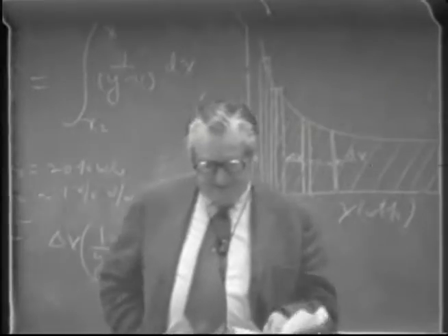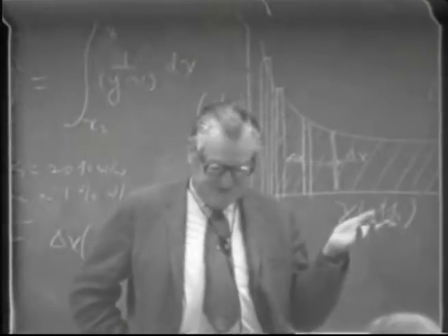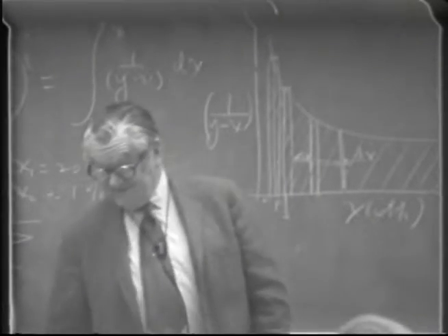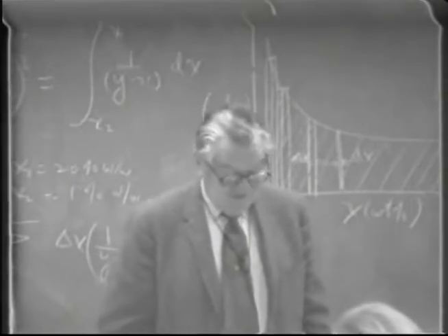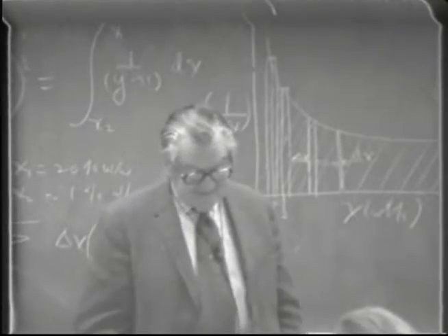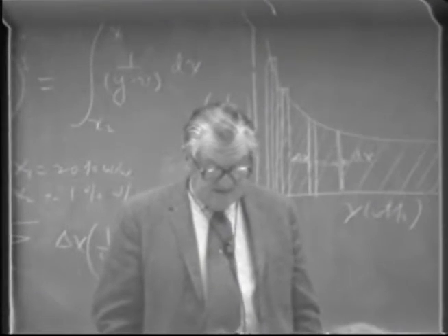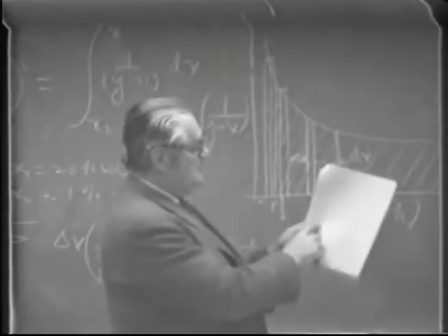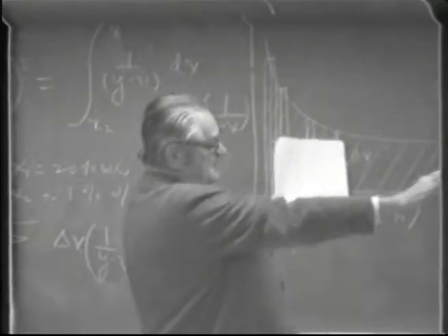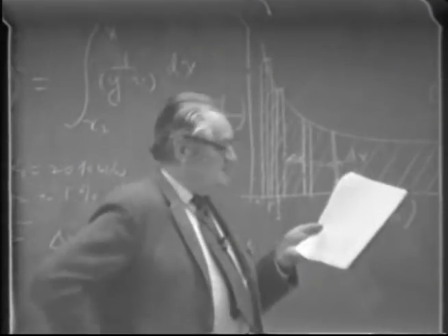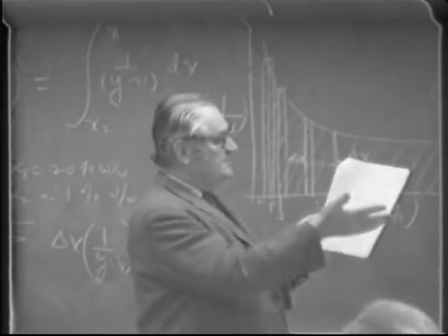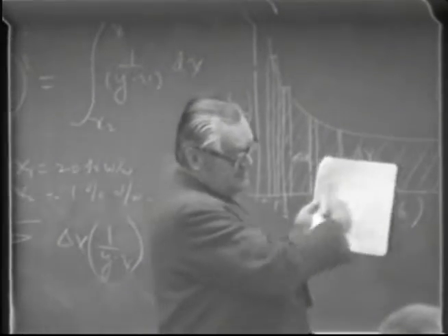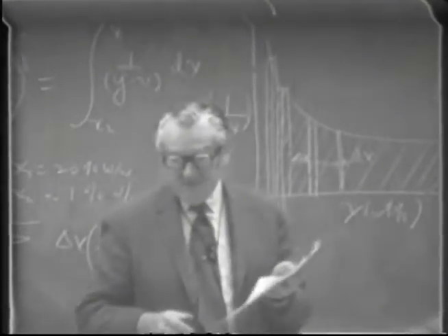And so I've done that for these hypothetical cases and plotted curves here. The purpose of this, at the time I did it, was partly to demonstrate to people that the amount of water added is very significant. The amount is important in getting a successful separation in practice in distillation operations. So you can see there, of course, that until you get a certain amount of distance out on the axis here, which represents the dilution ratio, you still have only one phase. And then when phase separation is initiated, you can plot these functions in terms of amount of water added.